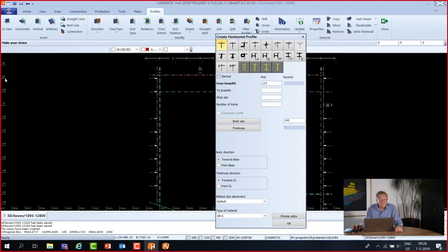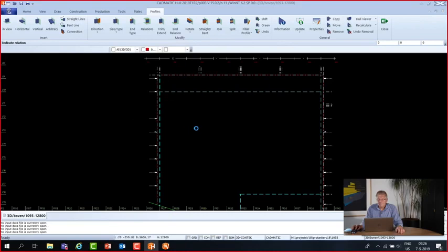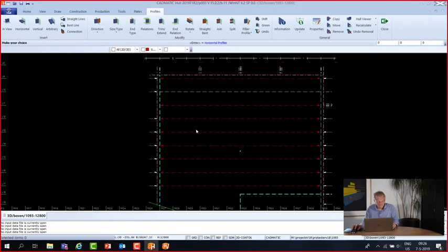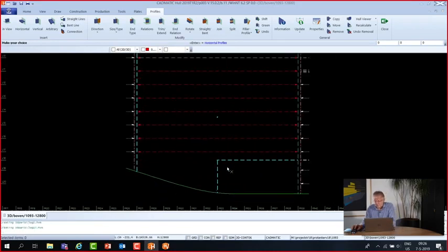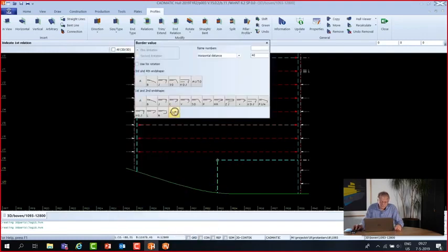So I'm using the grid. I'm starting at L9 and I'm ending at L17. They are displayed here, and I want to start at the aft bulkhead, of course with automatic end type, and end at the front bulkhead. And there they are. The same inside the tank, so Enter to repeat the last command, and that goes from L19 until L20, and from here until there.